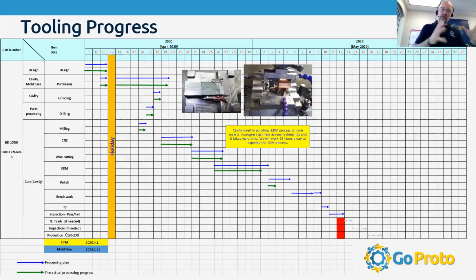And if we're making a quick tool, as Matt said, as we looked at those different types of tooling, a quick tool that's made in 1 to 3 weeks, I just need something quick that represents my drawings, that's in the right material. It may not be required to do that full validation process. But if you're stepping into bridge or production tooling, maybe multi-cavity, you want to make sure the different cavities are producing parts that are the same, then yes, we'd step into those next levels of inspection and analysis.